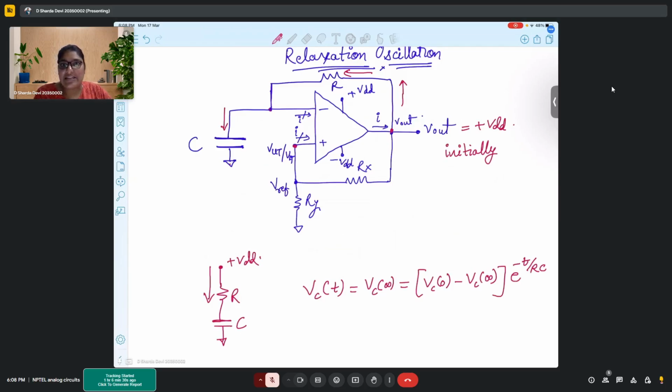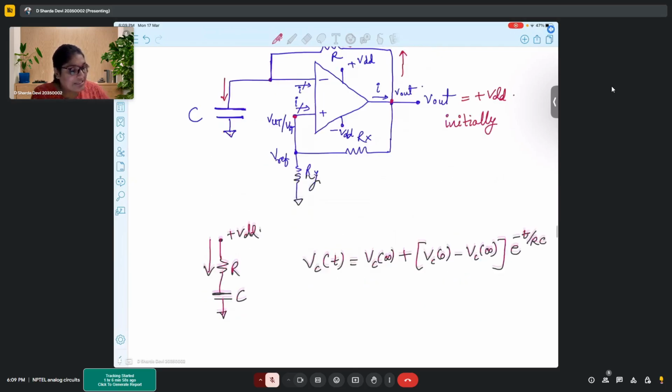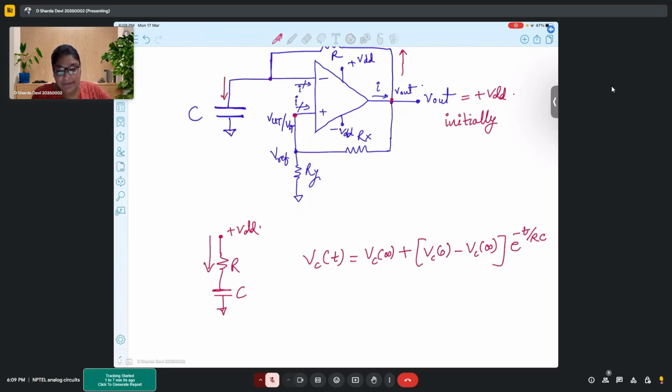It is a spike charging, so it charges very fast. Immediate charging happens, and similarly, immediate discharging also happens when there is no resistor present. The moment you connect a resistor in series with that of capacitor, your charging and discharging happens with a time constant, and that time constant is defined by the value of R and C, right? So this is the charging equation for my capacitor.